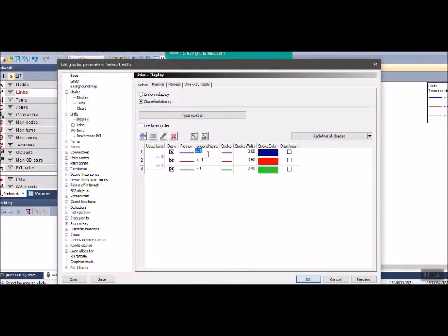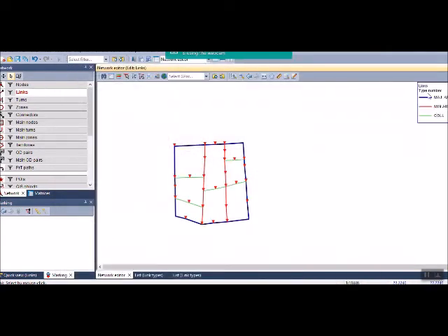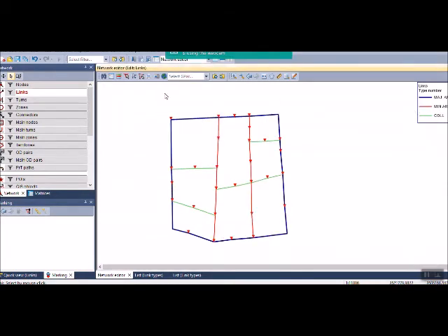Of course, you can change the legend name, which exists here on the right upper side. You can make it like this: major arterial, minor arterial, and this is the collectors. Okay, so the names are changed in the legend. Okay, so this is the road network well displayed. So we are going now to define the zones. The next step is defining the zones. So we are going to choose the zone in here and click plus.